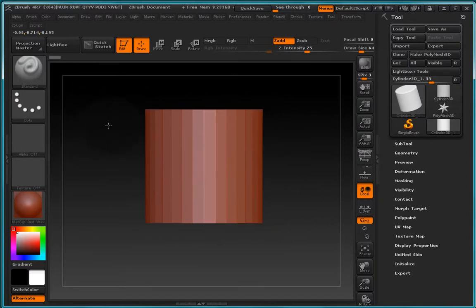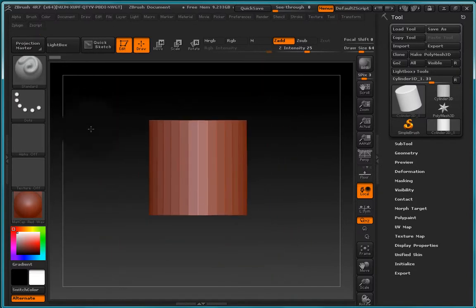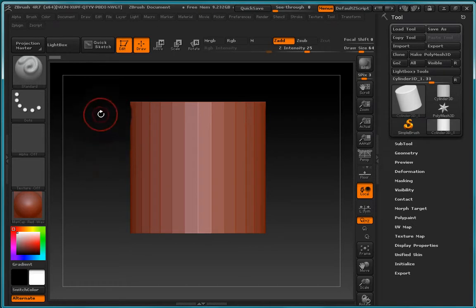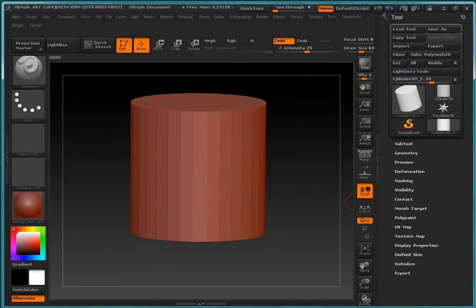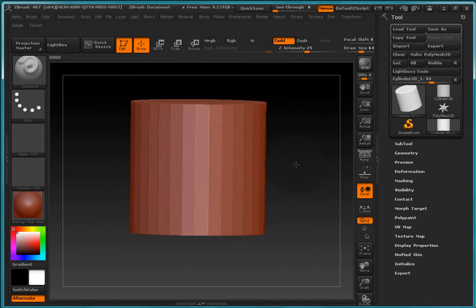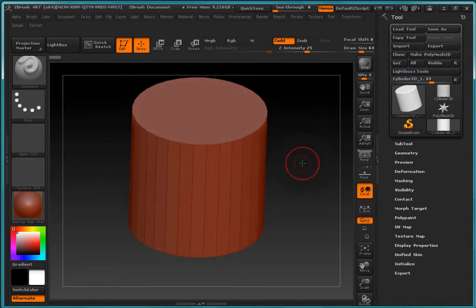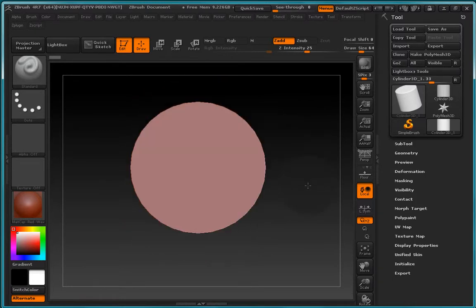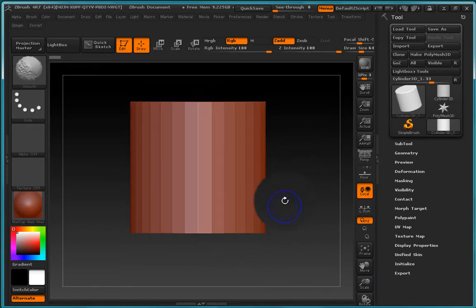If we are doing this and then let go of the left Alt, we can also zoom in and out. And if we left click on the outside of the primitive, we can rotate around here. If we are rotating around and hold the left Shift key, then we can snap to various angles, normally within a 90-degree increment.